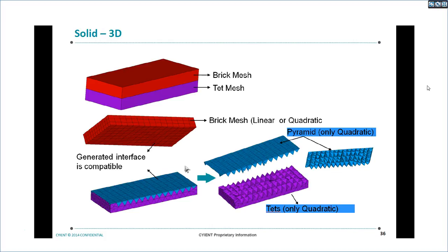Now, if I use the pyramid option, then when I try to mesh it with brick, tet, and pyramid, we get a very compatible mesh. If you see, we have quad faces here, so the same quad faces we are getting here, but it is coming through the pyramid option. Okay, so pyramids are found at all the interface locations, and these are all tets.